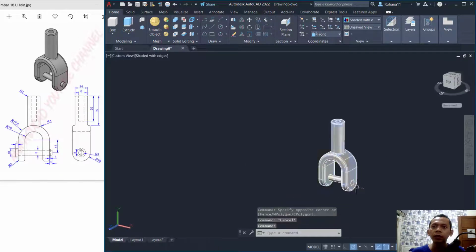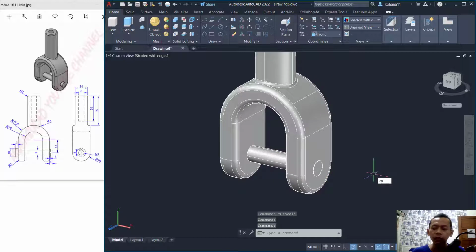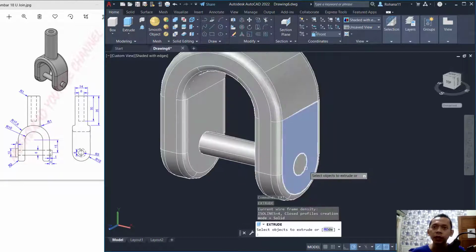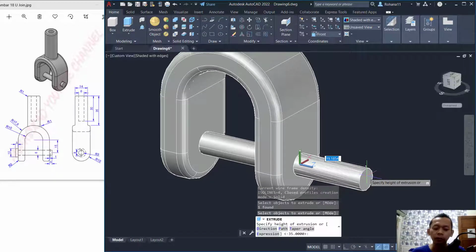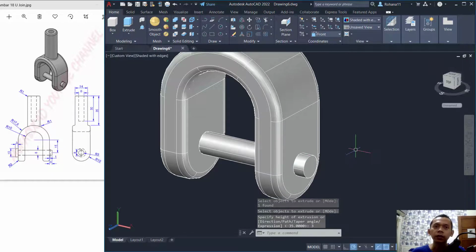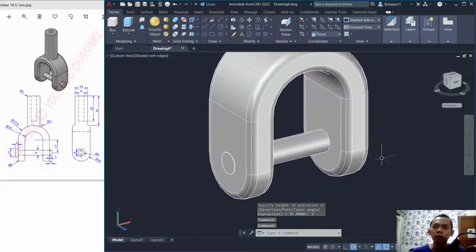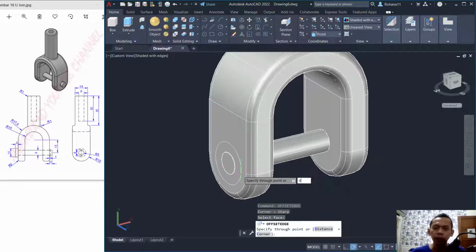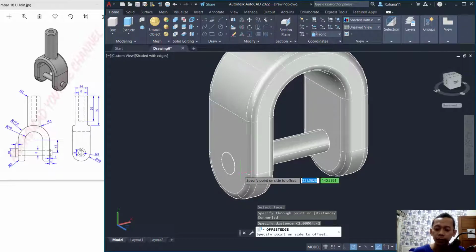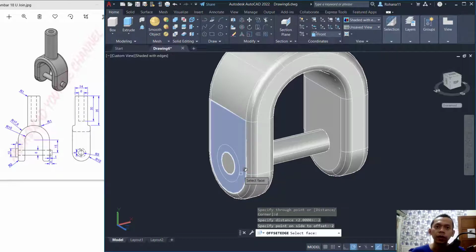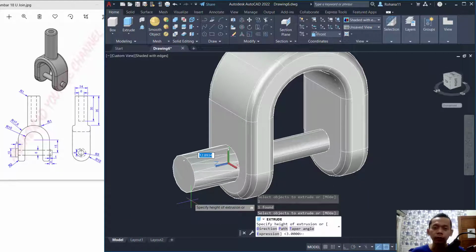And in here I will use the extrusion tool. Then tap extrude, select this face, hold the Ctrl button, click, and we can extrude about 3. Next we can create an offset edge. Select this face, we can offset with dimension, set to -2, enter, and -2 again. Next you can use the extrude tool to extrude the last object about 3.